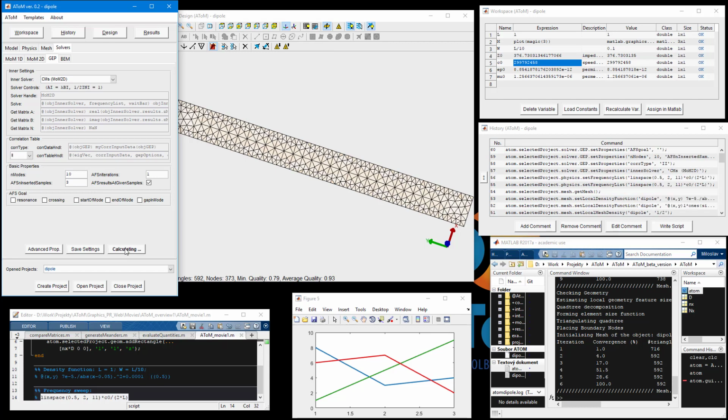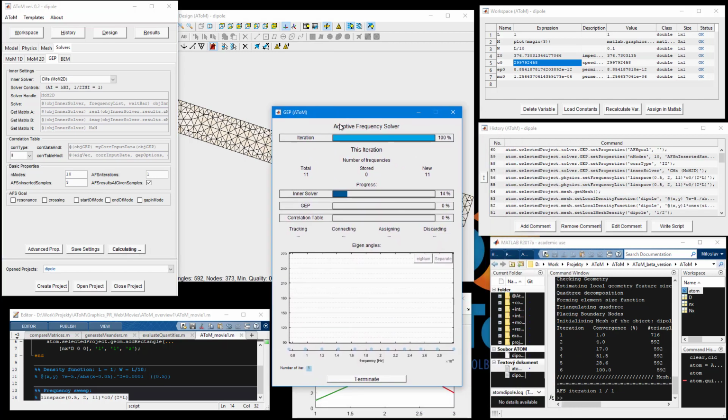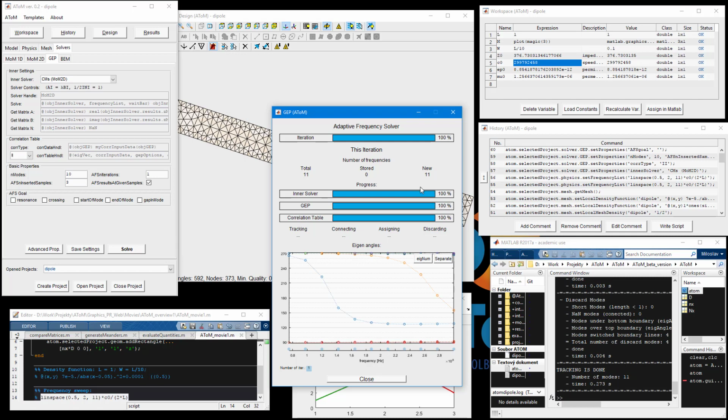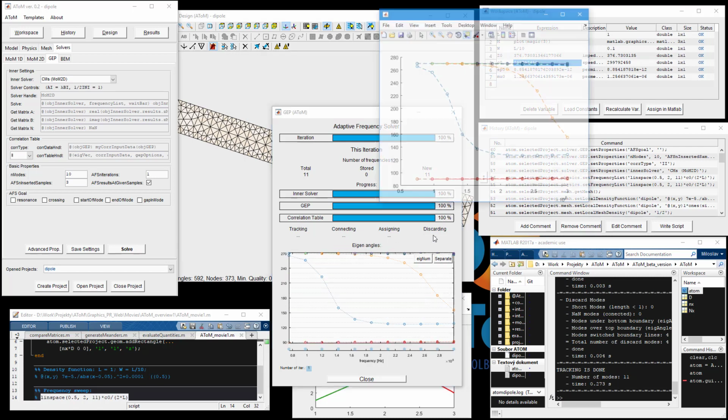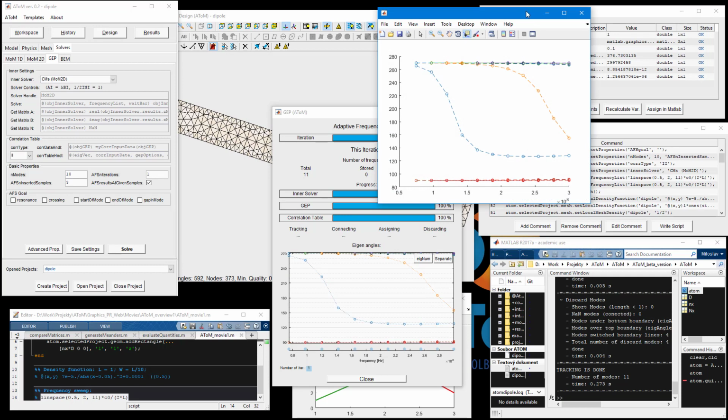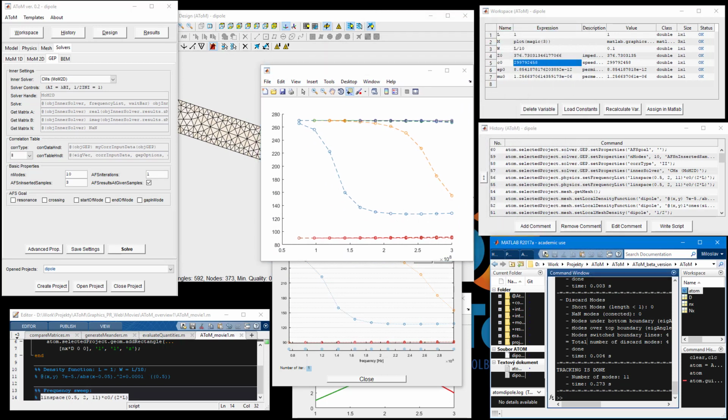The model solver has many options and possibilities. We will introduce them later in the problem-dependent examples. The characteristic mode solver is powered by the method of moment kernel, which supports symmetry planes, lumped elements, junctions, and other standard features.